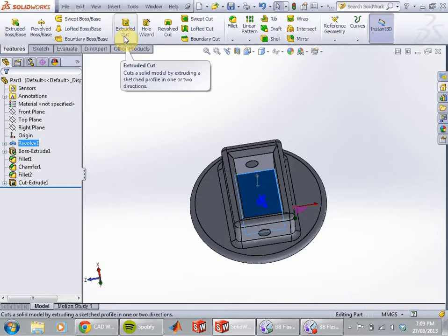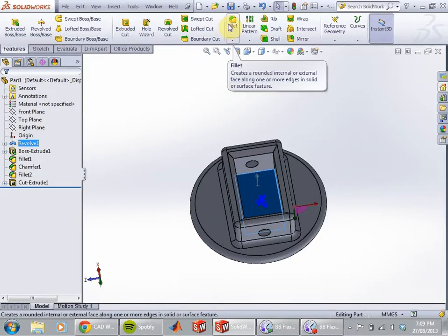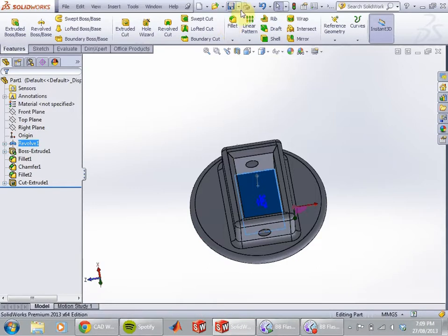And we're going to focus the rest of this on 3D printing. One of the things is stability, or a solid piece. You don't really need this whole thing solid. So what we want is to do a shell feature, and that basically clears out everything and makes a shell of your part.